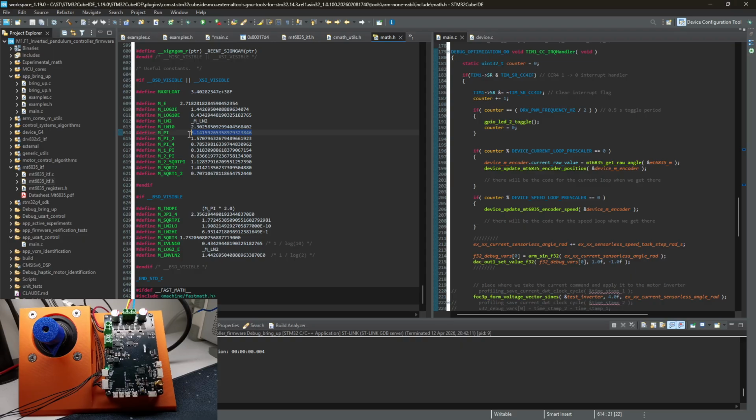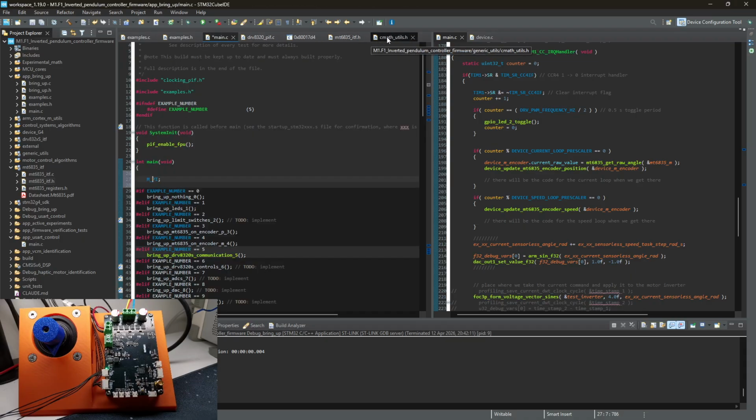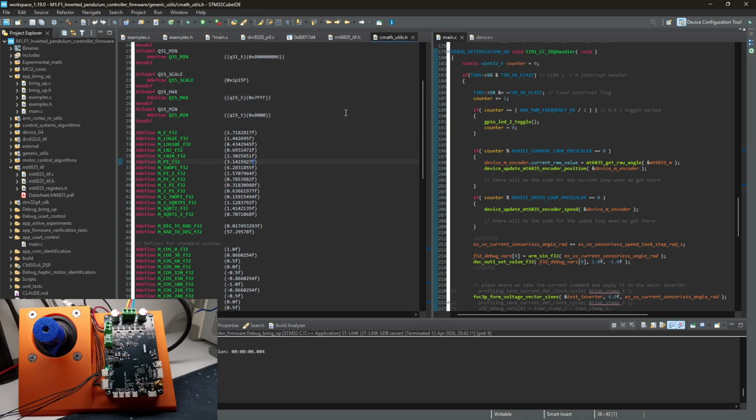And given that the FPU on STM32 only works with floats, the whole calculation was forced to be double, the division was double division, and after all the operations, the double value that was a result was converted back to float. And that was the issue. When I removed this value and added my custom definitions of math constants, it went from like 200 cycles to like 11. Actually, it was even less than 11. So the whole issue that I was debugging for more than an hour was just a float which is double.